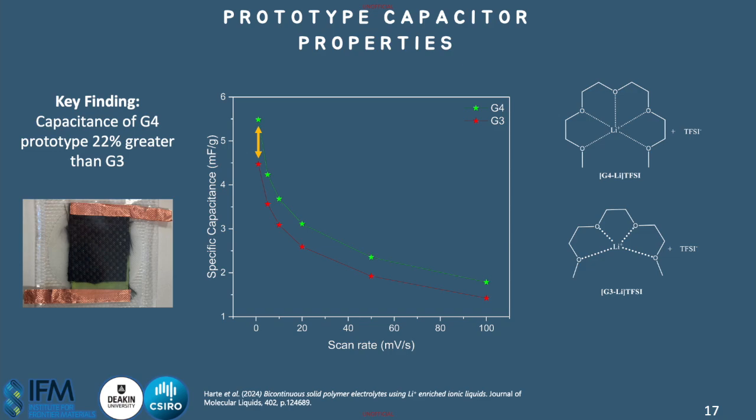So neither of the two capacitance storage mechanisms changed. Pseudocapacitance was not changed, as there were no redox active functional groups added to the surface of the carbon fiber, for example. And the surface area of the carbon fiber wasn't increased, so electric double-layer capacitance, EDLC, was not increased. However, the actual overall efficiency of the electrolyte contributed to improved capacitance in these systems.